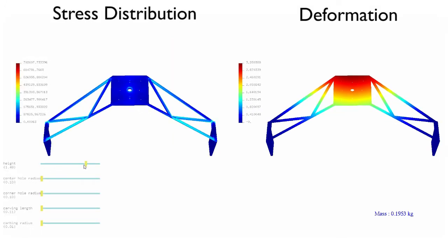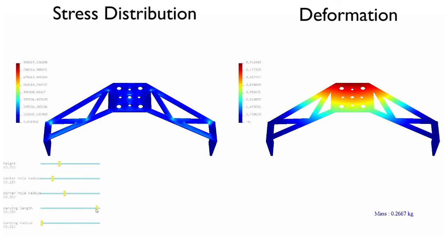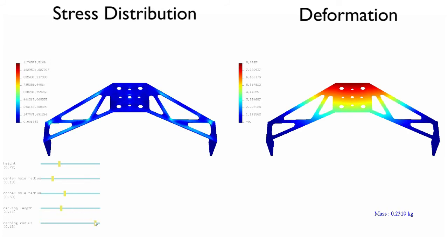In this camera mount, the engineer aimed at minimizing both the weight and the deformation on the connecting faces while making the stress distribution as even as possible. The holes were designed as circular patches to be fabricated with drilling, which is far less expensive than milling, and illustrates how our method can be applied for optimization with fabrication constraints.